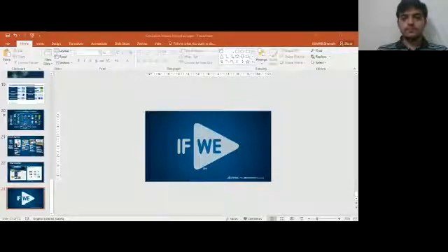Every time you manufacture a mount, there is going to be some variation. The variation can come from manufacturing, like manufacturing tolerances. The variations can come from the batch of material that is being used. So ultimately, in terms of the fit itself, there is variation. So what you could do is define these variations as input to your optimization model. Some of you might have heard about the Monte Carlo simulation. It is a way for you to randomly look at a distribution, and figure out what would be the impact of this variation on your output.